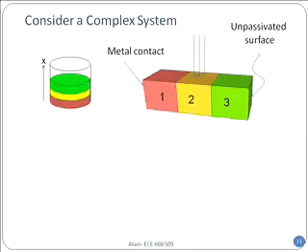In the middle yellow region, light is shining, right? This is an unpassivated surface, which simply gives you a clue that you should consider surface recombination. That might become important. So every statement here is trying to give you a clue of how to make the approximation.